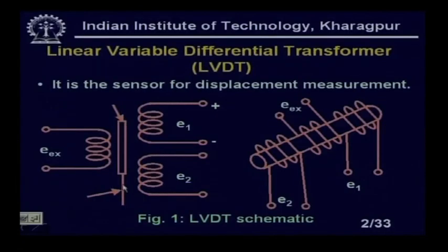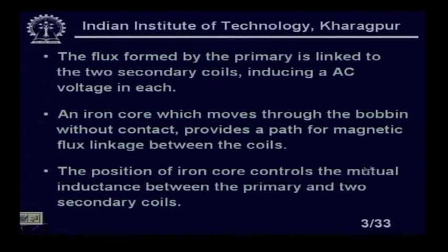Welcome back to the classroom again. So, we have seen the construction of an LVDT and how it works. If you look at this core, it will move up and down, and I will get different mutual inductance, the voltage also will change, and there will be a phase difference between the input and output. So, that is actually what we have written in a nice way.